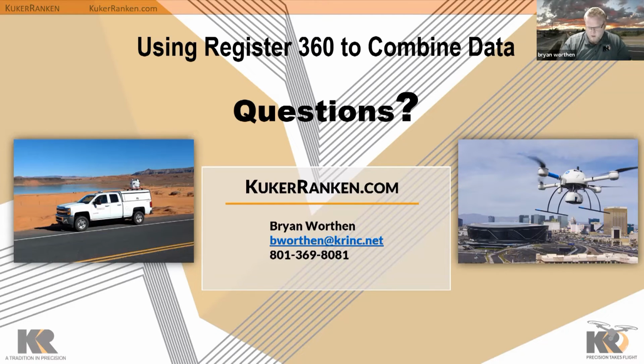It's really cool how Register 360 uses geometry now instead. So you literally just import it and then you right click on your bundle and you hit apply control. It automatically looks for the right geometry and the right targets and will add the control without having to sit and select things. So, yep. We have another question.